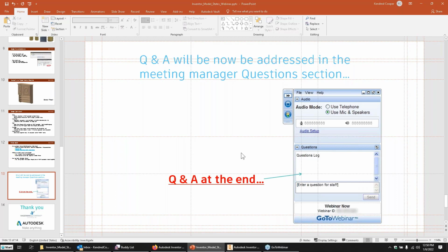How does this affect multi-bodied solids in a part file? And for sheet metal components, how does it affect the flat patterns? Flat patterns, you're still relegated to one flat pattern. The flat pattern will update based on whatever active model state is shown.